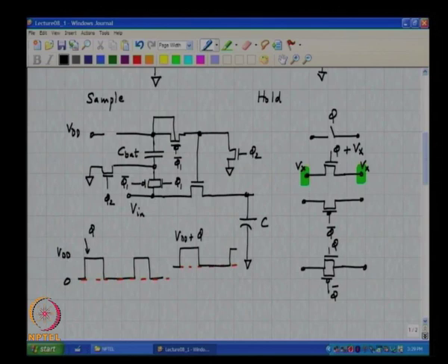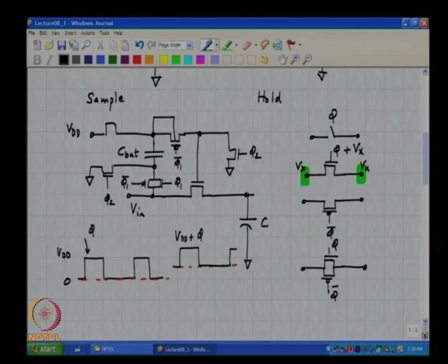So, Vx is now VDD, since the two potentials that we want to make the same are VDD, correct. So, what should happen to the gate based on our discussion just now? Instead of having phi 2, what should we do? We must have phi 2 plus VDD, all right. So, the next question is, how would you generate phi 2 plus VDD?